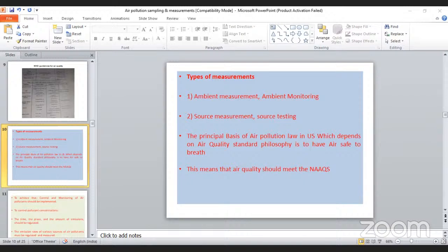Like that, it is connected in a sequence, and the entire setup is kept in the ice bath or cooling water supply system. Then after the study is over, we have to collect the solution from each bottle and mix all together. Then you take this to a laboratory for the quantification of the particular pollutant. This is the impinger method. Okay.